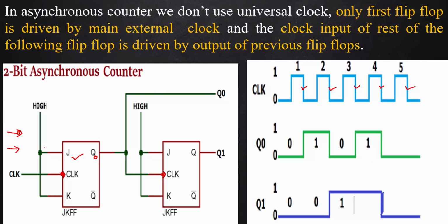Okay, these are some valid basic points that you have to understand in order to identify or analyze the block diagram of your counters. So this external clock pulse is going to trigger this flip-flop, and we are assuming negative edge triggering. Initially assume your Q0 is preset to 0.